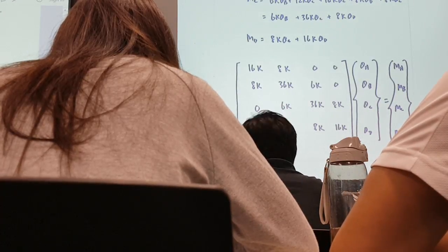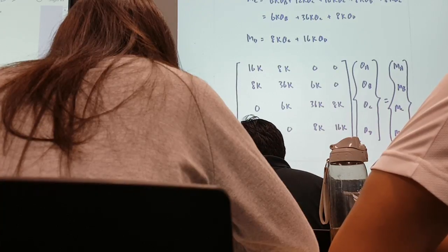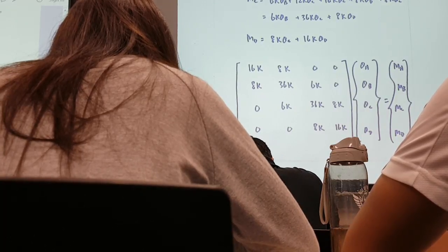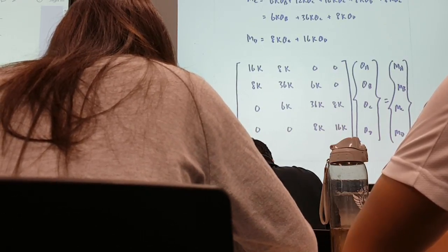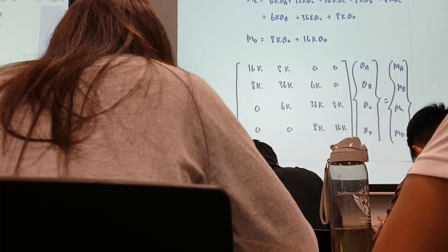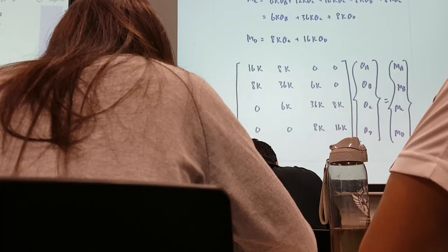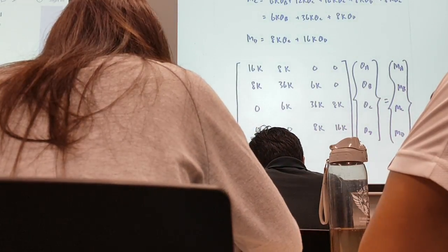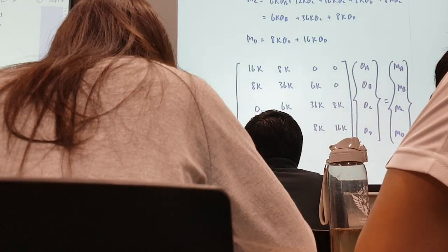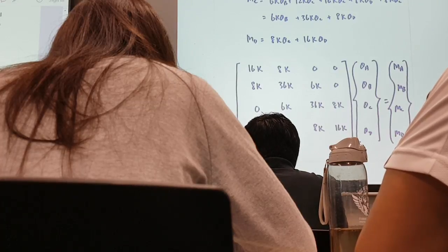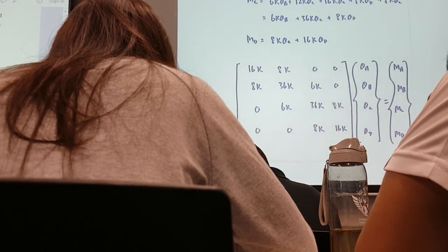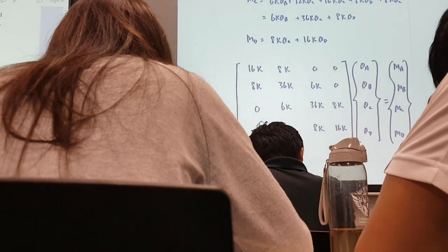So the distances have to go in when you calculate the M1 and M2, and even the PY1 and PY2. You will see the difference between the first question and second question is that the first question doesn't have any forces. You can see that question 1 doesn't have any forces involved, so you only calculate the moments. But in question 2, there is a uniformly distributed load acting at member BC. What form of loading is this uniformly distributed load? Is it a load on nodes or a load between nodes? Along member BC, you have to know that it is between nodes, because this uniformly distributed load is applied between nodes B and C.